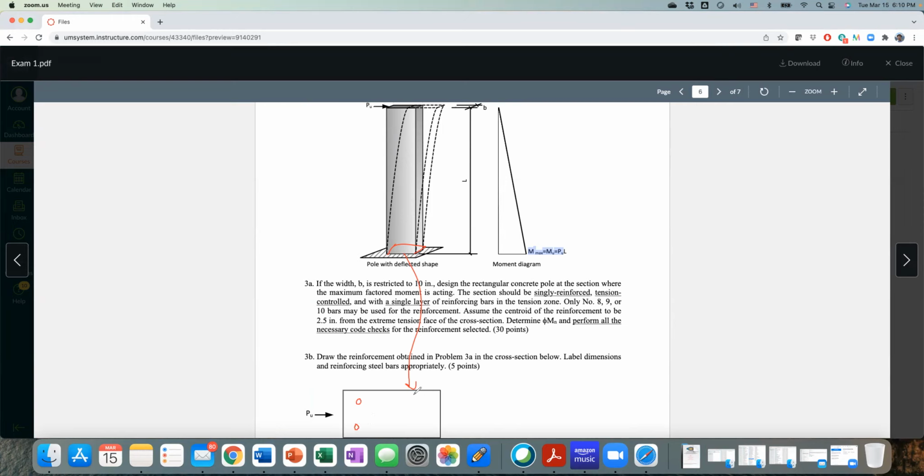So when you design the section, you have bars, and I'm putting 2 bars here, not necessarily meaning only 2 bars, right? You may end up with 3 bars, that's up to you. But when you draw that, you also need to draw the stirrups around it, and also give me the spacing, give me the details. What is the spacing, and then find out whether this section actually checked out in terms of beam in or not. So things like this need to be checked for your sections.